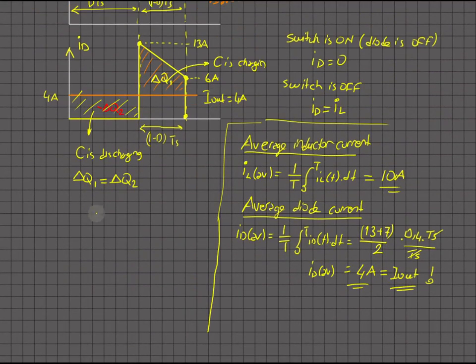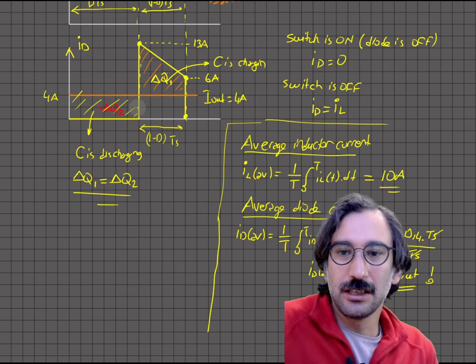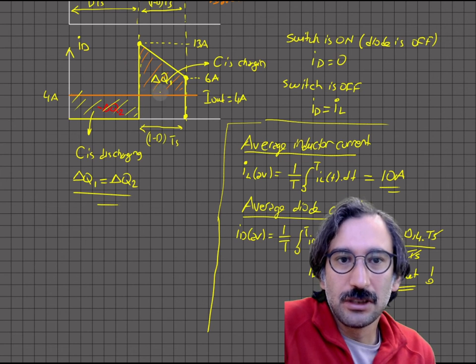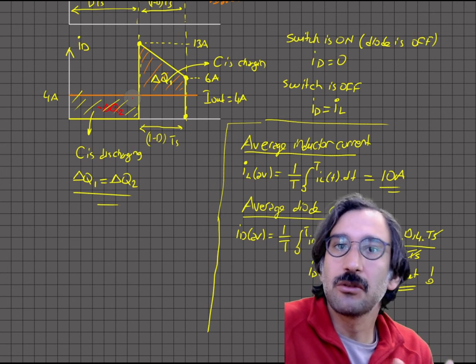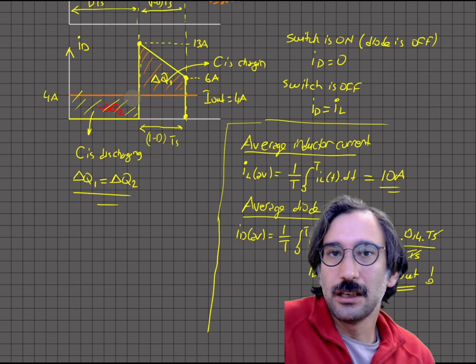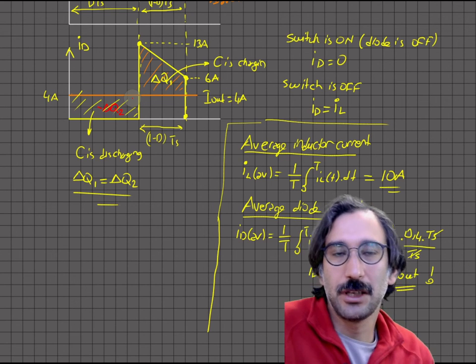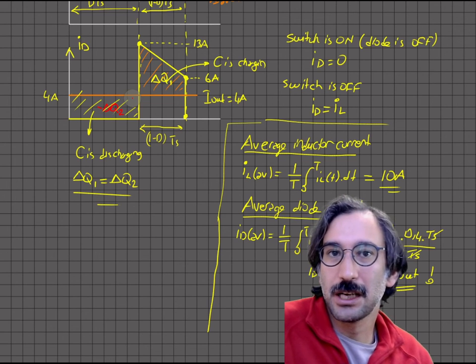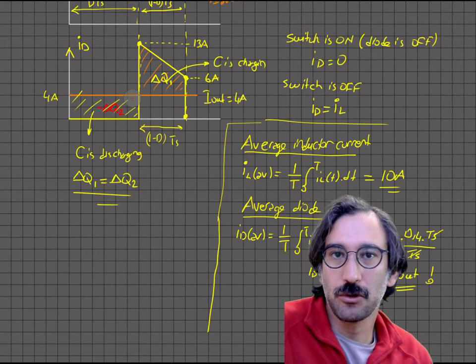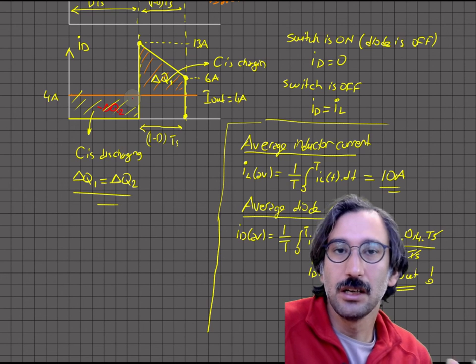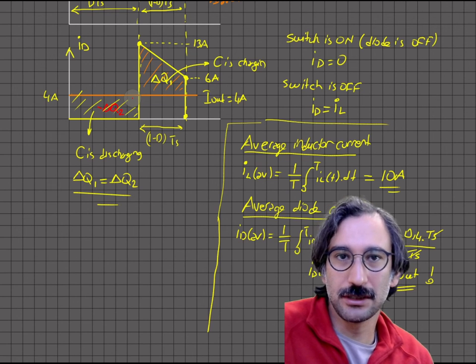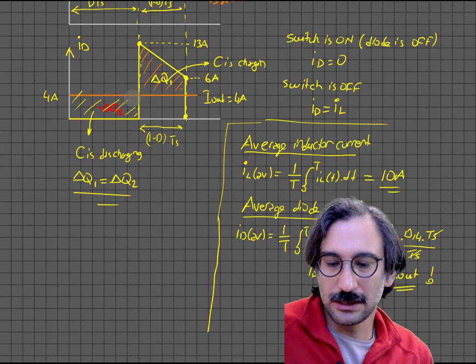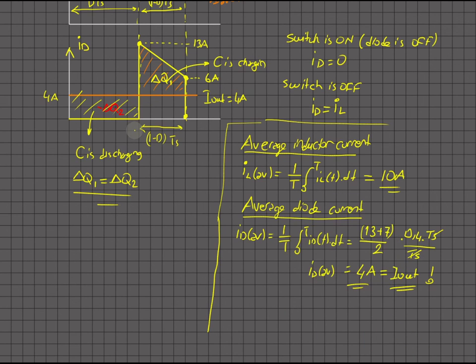So then let's calculate those ones. And again, the selection of the capacitor size is totally dependent on that one. There is not a certain rule, but if you want a high quality boost converter, you can put a large capacitor size. You can have really minimum voltage ripple, but sometimes the volume is limited, or there are some constraints on the maximum cost of the converter. So you want to reduce the cost of the capacitor, so you choose a smaller size. So let's calculate the ripple.